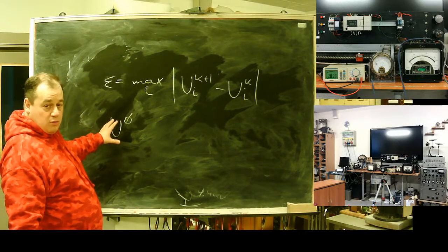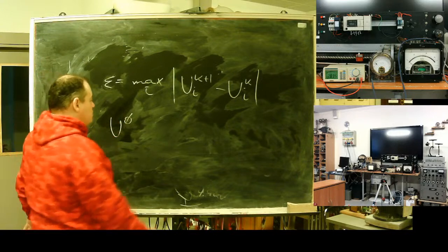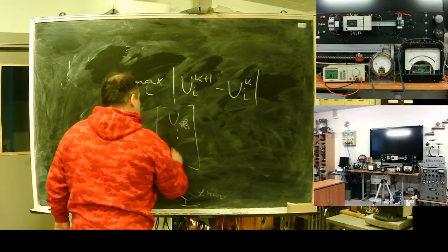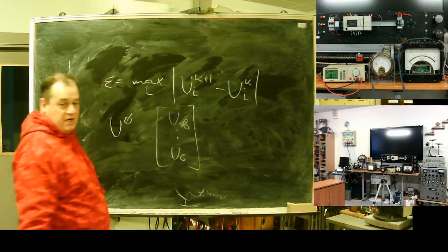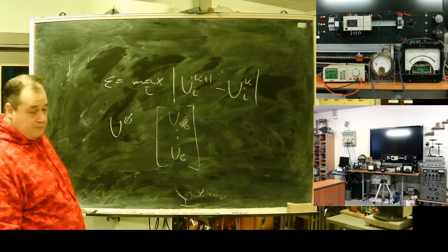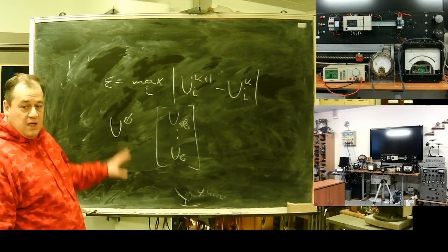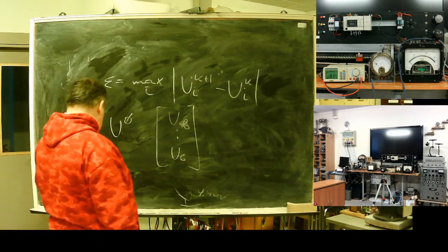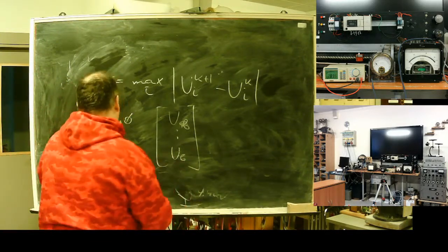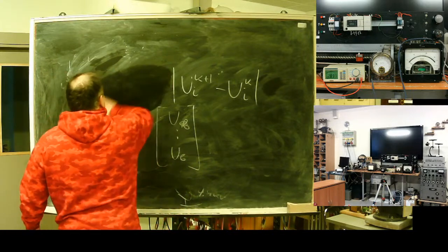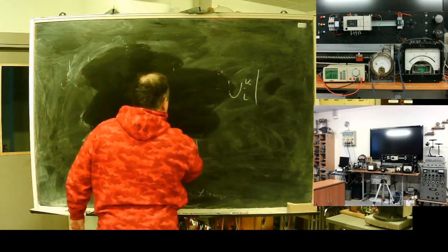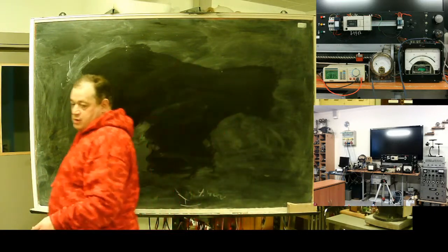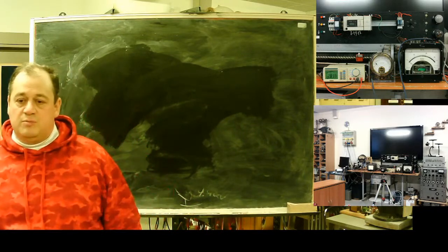If you don't know some trusted regime, just use a vector of base or slack bus voltages. No problem. But convergence is dependent on network load. When the network is near its transfer capacity, the method will converge with problems. But let's assume it's converged.